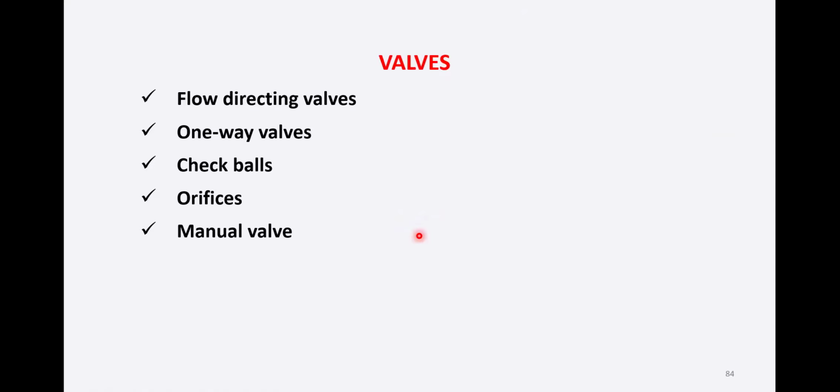Now, the manual valve is a spool valve that is moved by the shift linkage. All valves in the valve body have sharp edges on the lands. Any dirt in the valve body area can cause shifting problems due to the close tolerances between the valves and the bores in the valve body.